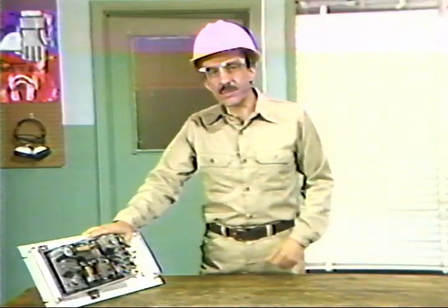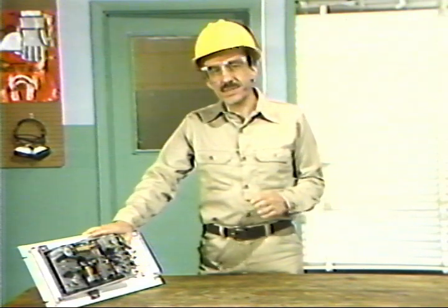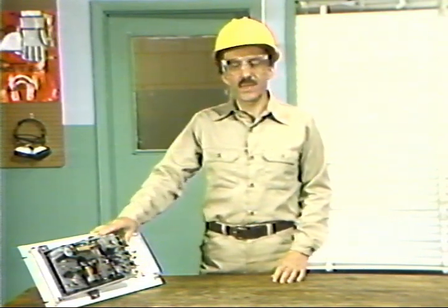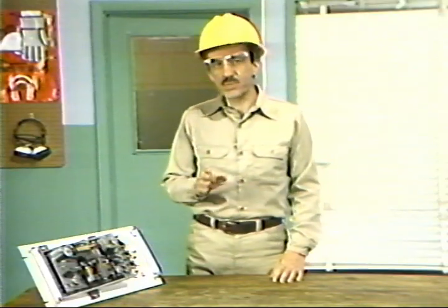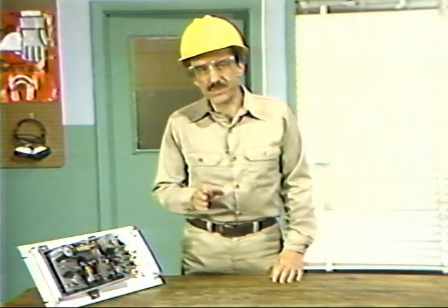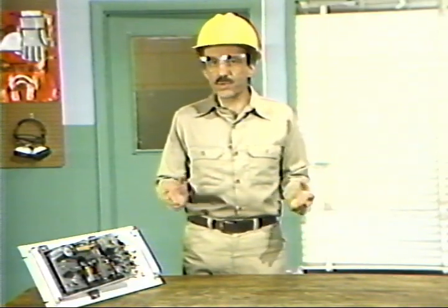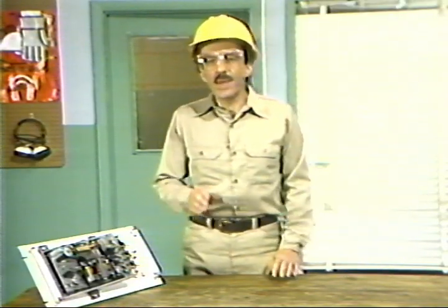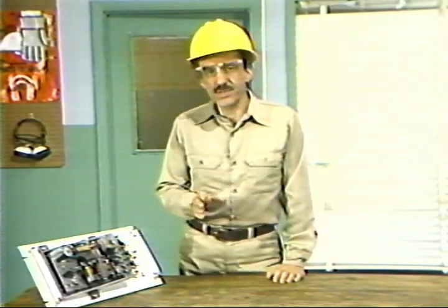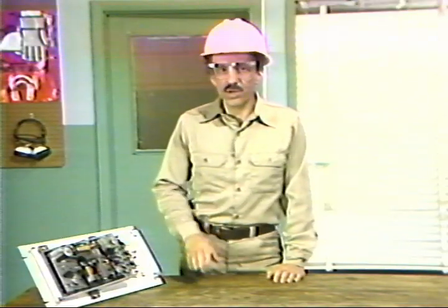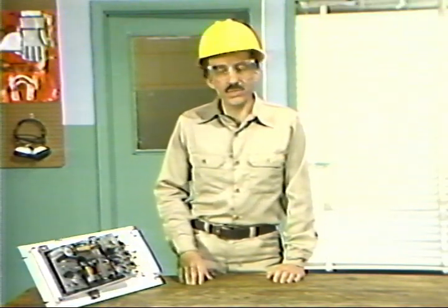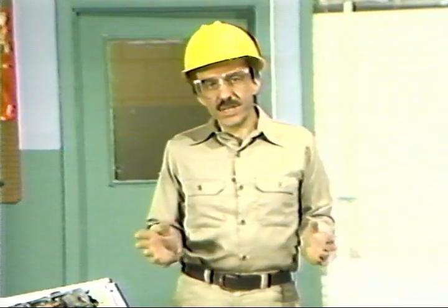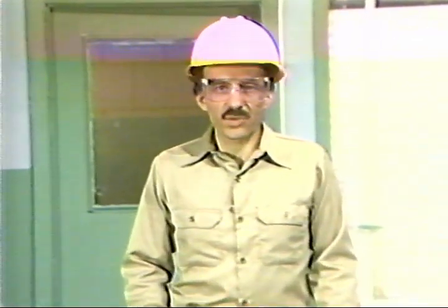This controller, like many 3-mode controllers, has a number of different switches and adjustments that are covered in your text. It's important to make sure you have the switches and adjustments in the right positions. Otherwise, the controller won't provide the appropriate control mode for a process. Make it a habit to read the manufacturer's instruction manual before you work on any controller or tune a control system.